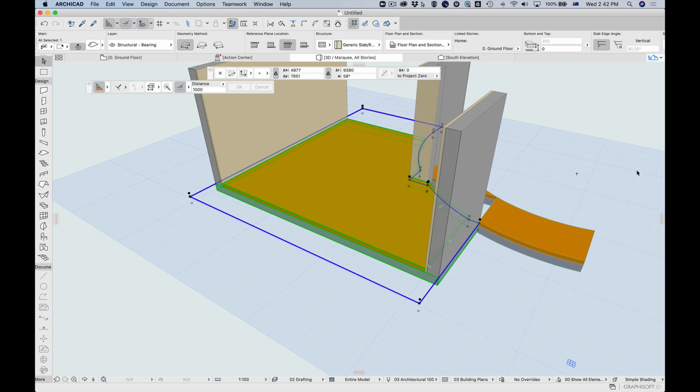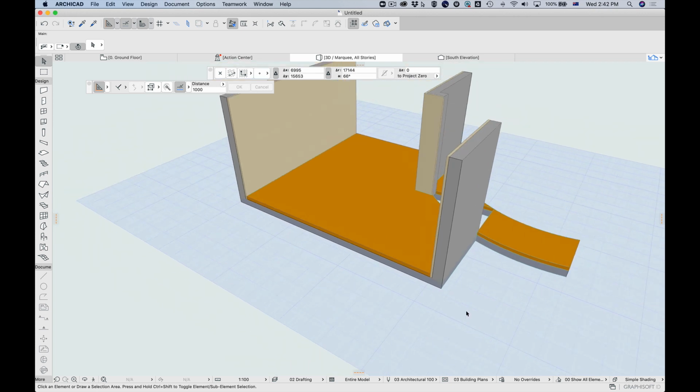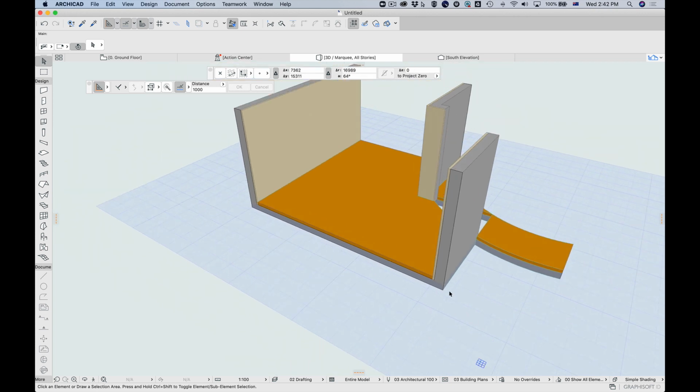Those snaps, I can't stress how important it is to always snap things to the correct points. It makes life so much easier. If you just eyeballed that, there will be a slight difference there, and then when you do cross sections or detailed drawings, all of a sudden you notice all of these little mistakes. Or the worst one is when you dimension stuff and you end up with weird dimensions that just don't add up, and it's because you never snapped to the elements you should have.